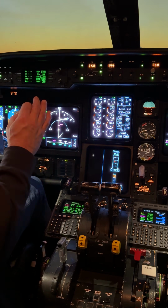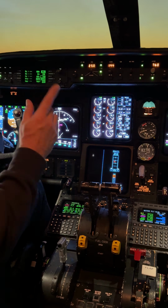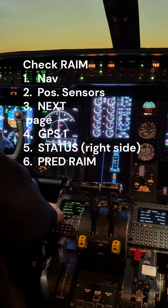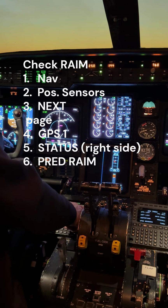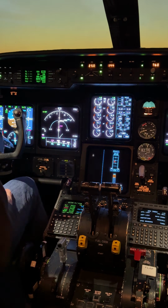Remember, this is an RNAV approach, a GPS approach, so what else do we have to do? Yes, check RAIM. Let's do that. NAV, we can do it over here. NAV, position sensors. Next page, find GPS 1. Select status on 3 right. It says predict RAIM. That's 4 right, and the answer is yes, we have it. We'll go back to our flight plan now.